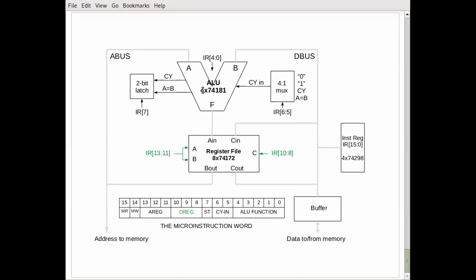The register output on the D bus is specified by 3 bits of the instruction word, and the address, the A and B, are now specified simultaneously with the A reg field, three other bits of the instruction word. I have not yet tested this or implemented it. I haven't done the hardware, certainly. I was going to do this as a printed circuit board, but never got around to it. I'm going to implement this with the simulator as soon as I get the simulator for the original version working. This actually can save a few instructions. I've coded a few primitives, and this can save a few instructions. So this is going to be the PISC 1A. I don't think it merits a 2 yet.